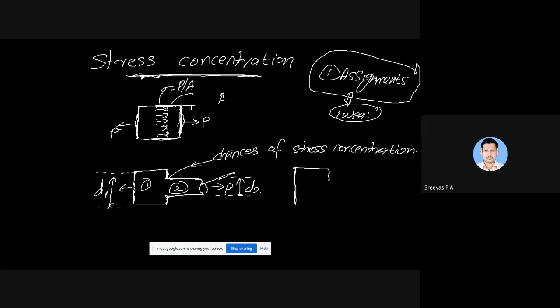We will make it with some chamfer, we will make it curvy, so that you can avoid it to some extent. So that is the basic idea behind stress concentration.